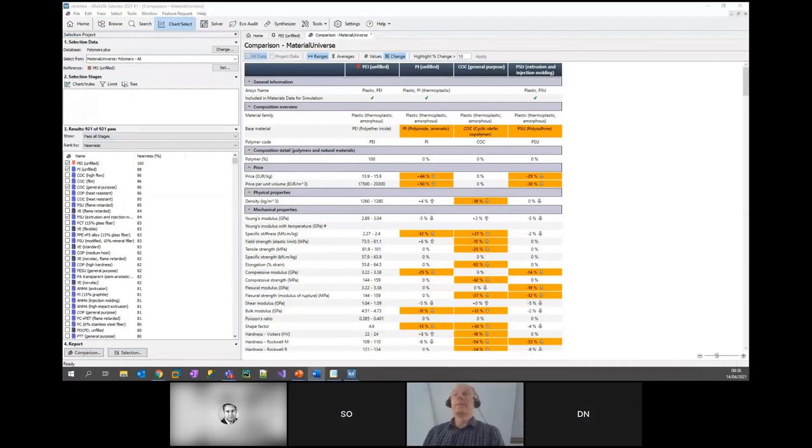Sorry, 921. Okay. So the first process I'm going to do is try and work out, can the product be manufactured with this material in a suitable way? So we've identified that injection molding is the way that we're going to work. And what we can do is filter out all the materials that don't have a link to this particular process. So we have another table of manufacturing processes, and we can filter out anything that isn't